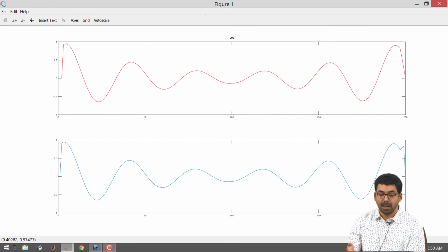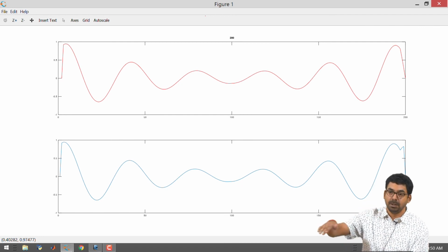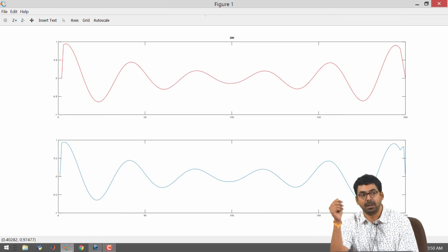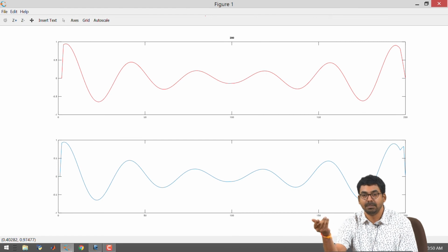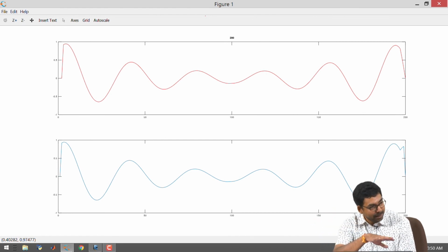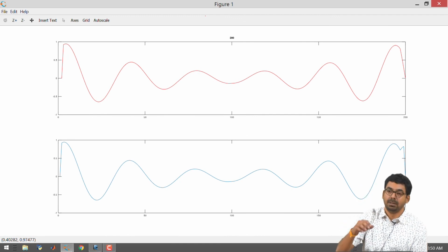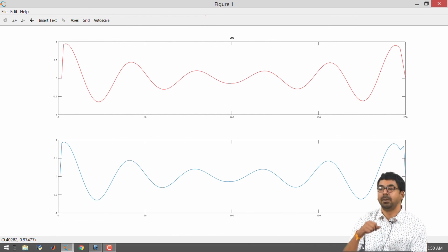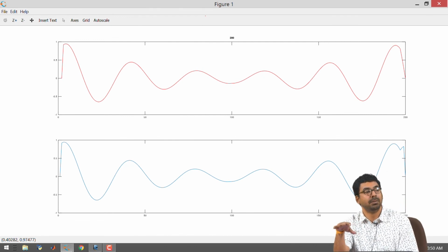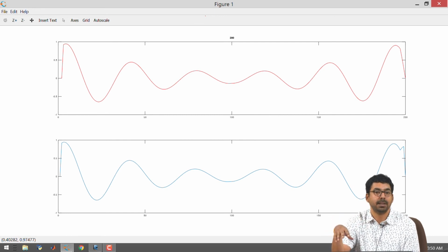There is also another way of looking at it. Suppose I just had a loss, I did not have the gain at all, and the magnitude goes to 0, a receiver will receive no signal with respect to time. The assumption that you make when you do not receive any signal is that no signal has been sent. So, you need to know what is happening inside the transmission line, and you need to know the spatial information and the temporal information. Together they will tell you what the wavelength is in different places, what the loss is in different places, what the velocity is in different places, and how much delay I should design my circuit to withstand. All these things are important.